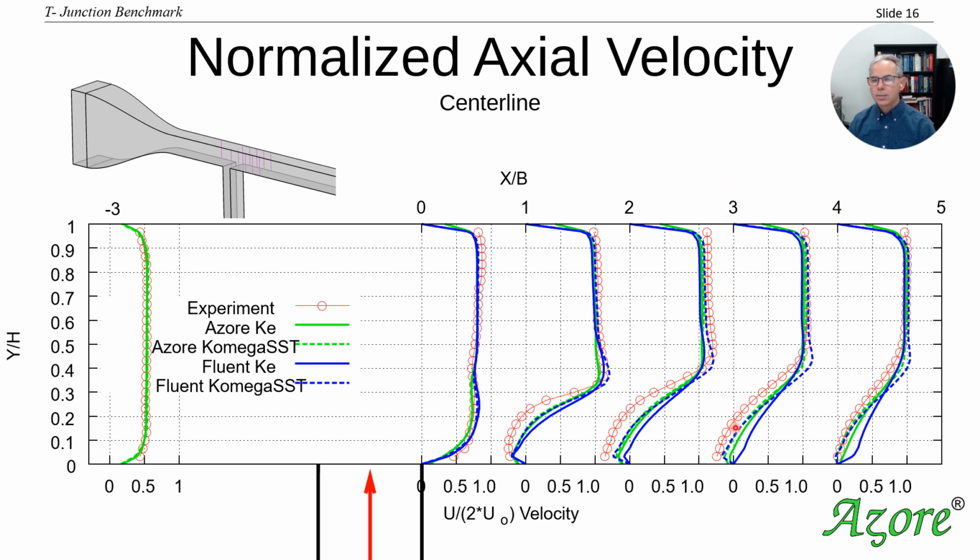And when they're behind the reference line, what that really means is that the velocities are going in the opposite direction. And so that's basically, we're in that little eddy that we saw in the fluid path lines. And the velocity vectors, you can see this is where the velocity is going in the reverse direction. So basically on this line, we can use this to look at the differences between a software package's prediction and the experimental data.